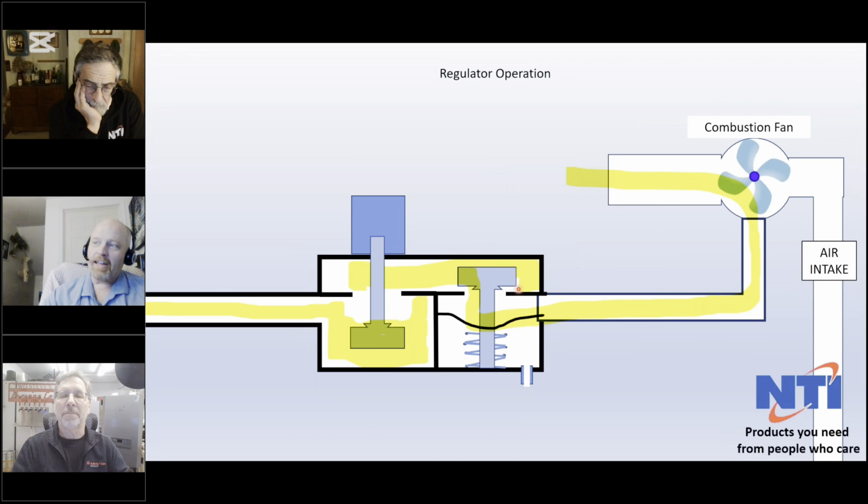The only way to get that kind of perfection is to probably spend $1 million on a gas valve, and each individual valve would be $1 million. Or you have electronic feedback, which is why a lot of cars, of course, have gone to electronic fuel injection. For the purpose of what we do with the boilers, typically what we'll see is a couple of tenths of a percent CO2 change from summer to winter. So it's such a small change that it works so well that we just don't have to worry about it.